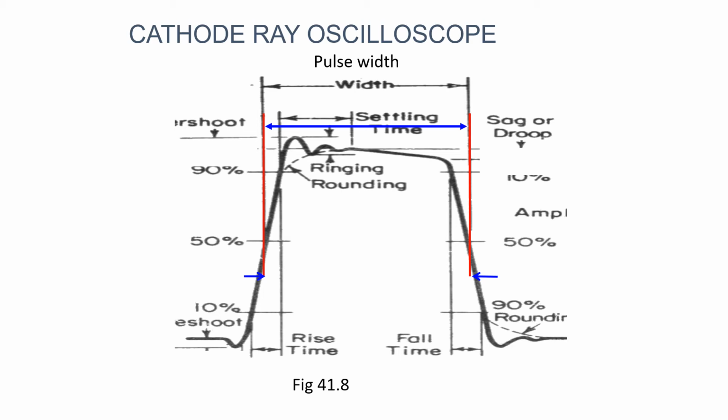That is, a waveform with steep leading and lagging edges, and a practical pulse waveform, that is, which has the rise time and fall time. So if you give a waveform at the input with steep rise and fall times, and if the output is a pulse with noticeable rise time and fall time, then there will be a delay time which has to be measured.